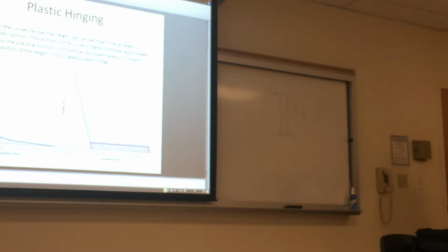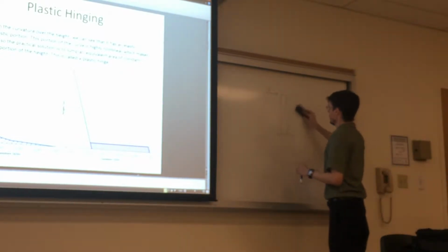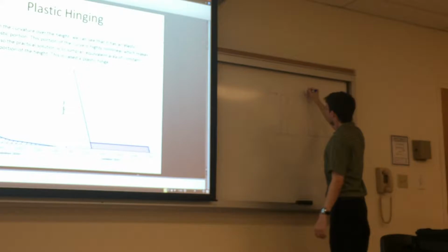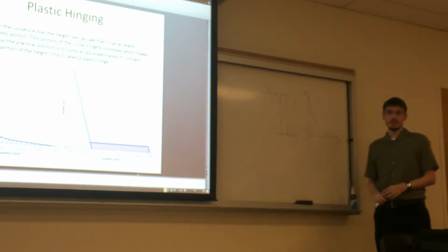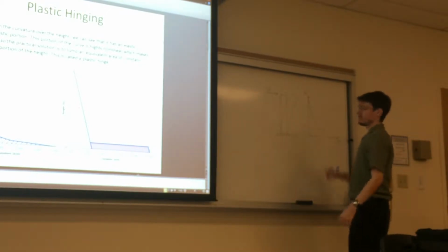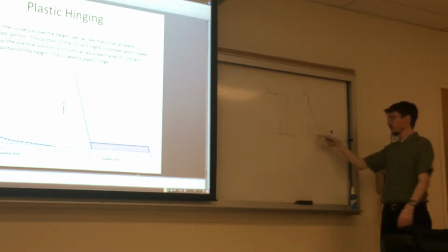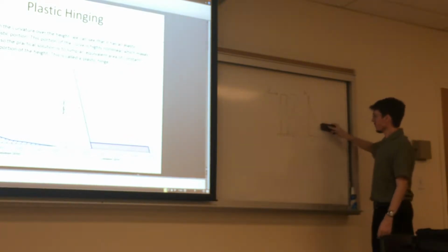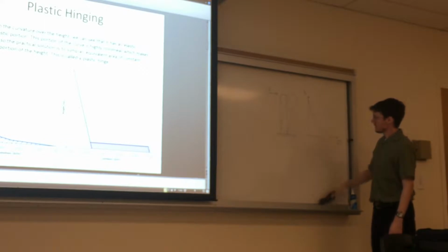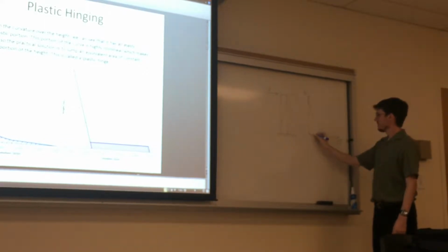So you could look at, let's say, the height versus curvature, and you come up with, then, if you're looking at, say, h versus curvature, it looks something like this. You're looking at, let's say, one of these cross-sections of interest. Generally speaking, you look towards the base, because that's where you have the maximum moment and the highest level of curvature, right? So you generally want to look at, essentially, this cross-section way down here.